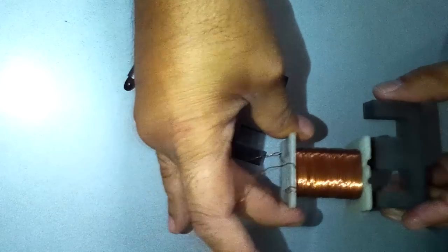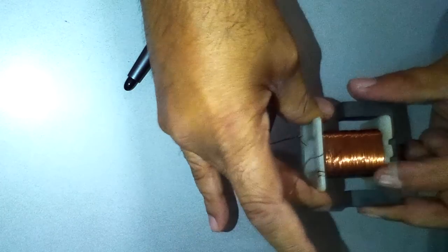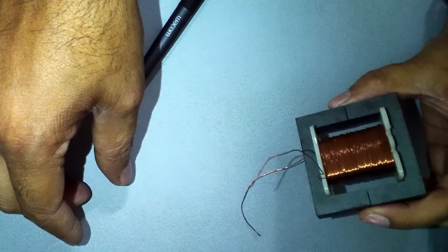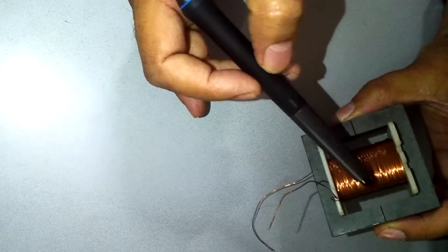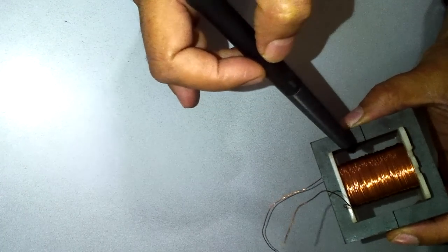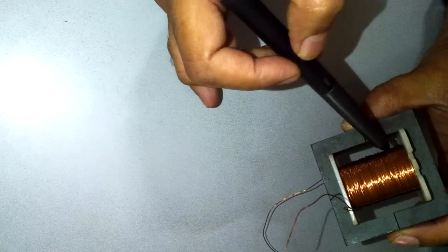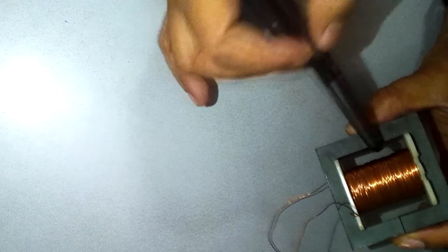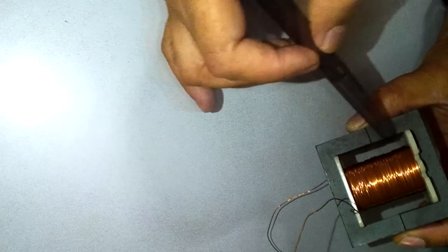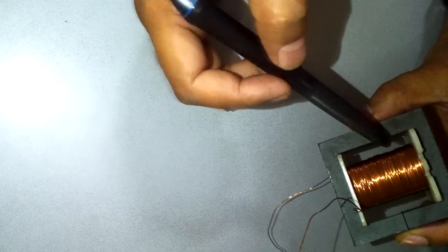So then after winding, the bobbins are inserted into the core to form a completed transformer. So you will see that here this portion is the window area which I was saying, and the windings fill up here. So if I make a cut section, you will just see circles of the copper here in the window area.